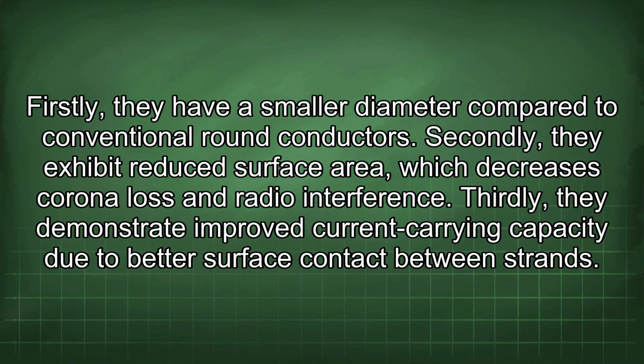Firstly, they have a smaller diameter compared to conventional round conductors. Secondly, they exhibit reduced surface area, which decreases corona loss and radio interference. Thirdly, they demonstrate improved current carrying capacity due to better surface contact between strands.